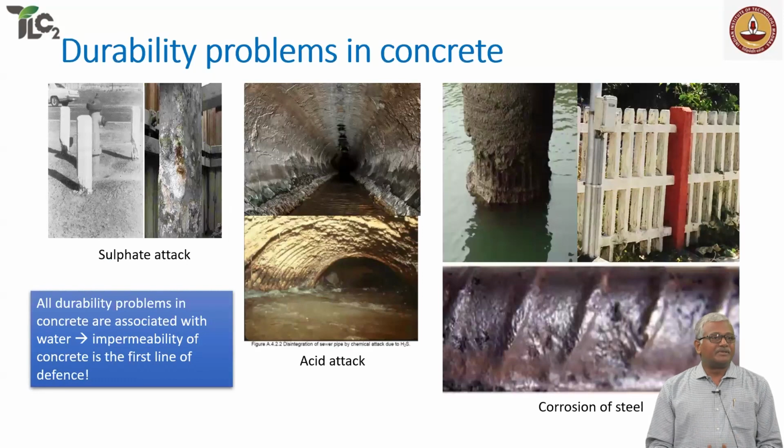Now, you all know very well that concrete is subjected to a host of durability problems during its life cycle, depending upon the kind of exposure environment that you have the concrete working in. You have external sulfate attack, which is brought about when you have concrete in sulfate-rich environments. In some conditions, the soil has a lot of sulfate. In some conditions, the water brought by the groundwater, or maybe brackish water, can have sulfates and chlorides in it.